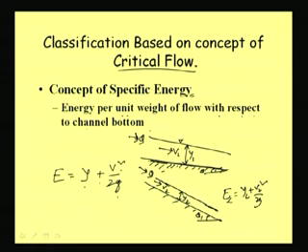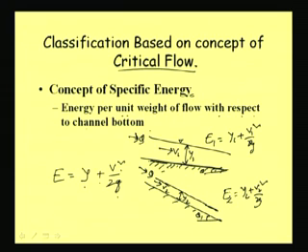by twice g, and for the first it has energy E1 is equal to y1 plus v1 square by twice g. Now just concentrate on these two equations. Is it possible to say whether E1 is larger than E2 or E2 is larger than E1? It is definitely not possible just by observing, because there are two terms, one is depth, another is velocity.